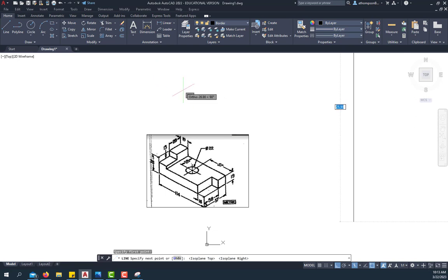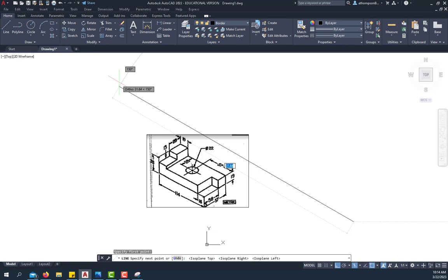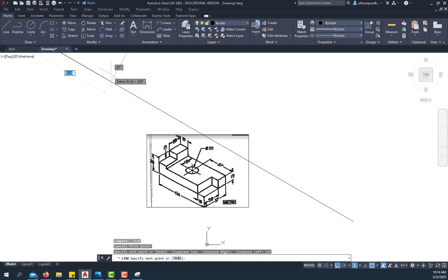So iso right will not let me put in a width dimension, which makes sense because I see height and width in the front view and width in the top view. So you have to be in the front or top planes. So as I'm taking this object back to the left here, I'm going to type in 114.